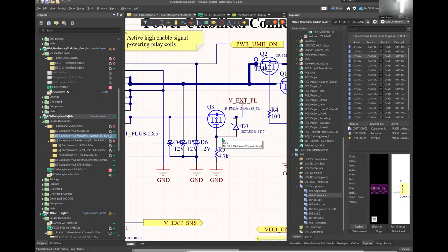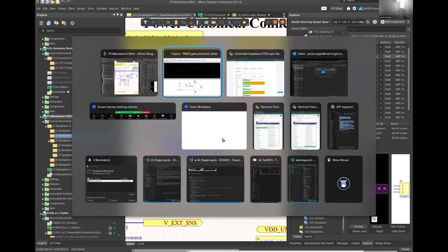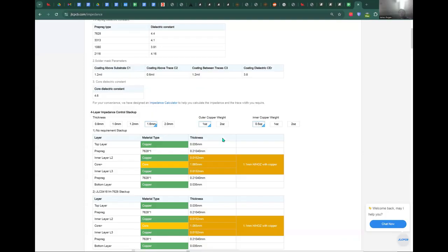And there's obviously a lot more going on on this PCB than I've simulated with just that one subcircuit. But with my knowledge of the design, I can know that if I simulate that subcircuit, there's probably nothing else on the board that's going to affect its behavior in any way that will make the simulation invalid. So in that way you can abstract away everything else. So that's a little bit about simulation.